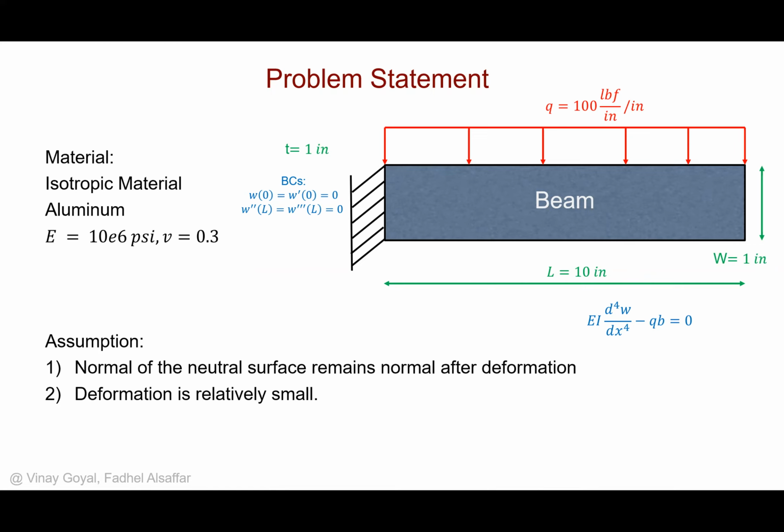And then we moved to use 1D, and within 1D we used the linear element, and then we used the cubic element, and we saw that within the cubic element we got the exact solution. And you can see that within that 1D formulation, you can get the exact solution even if you're using the student version of Abaqus, because all we needed was 100 elements.